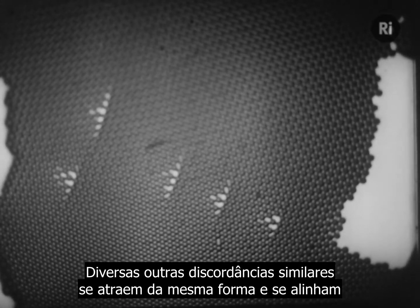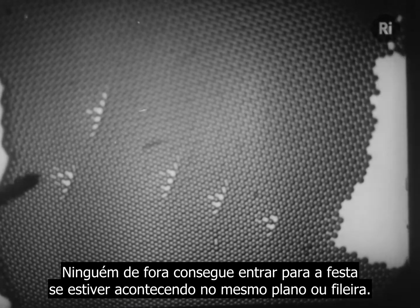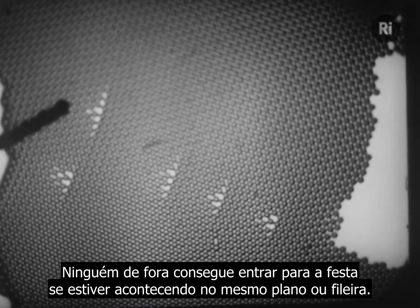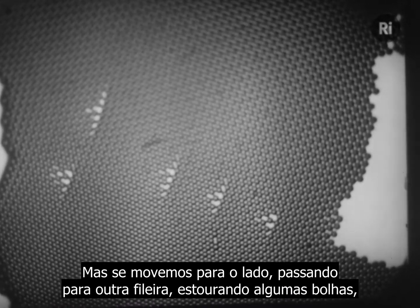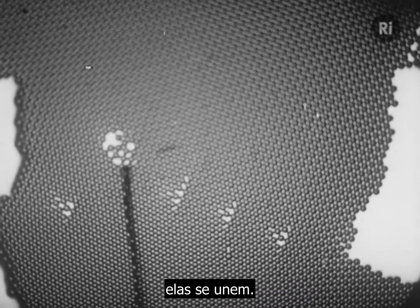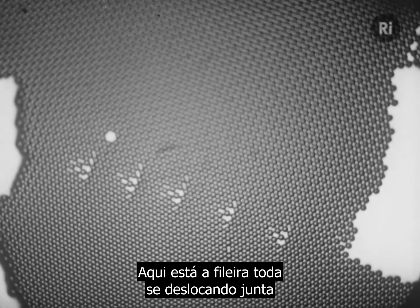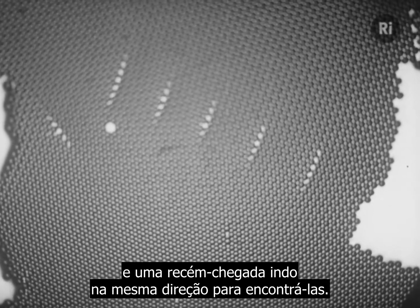A number of similar dislocations attract in the same way and line up. An outsider cannot join the party if it's on the same plane as one in the row. But if we move it sideways onto another row by bursting a few bubbles, it joins up. Here's the whole row moving together and a latecomer hurrying to join their company.